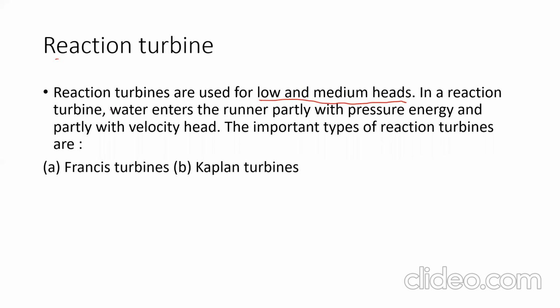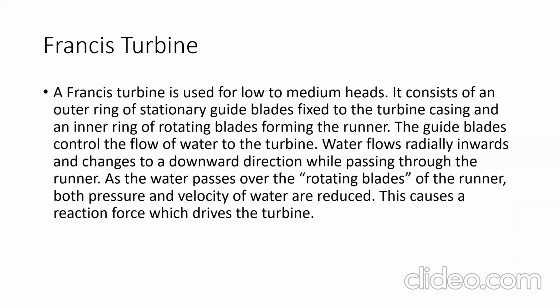Reaction turbines are used for low and medium heads, whereas impulse turbines are used for high heads. In a reaction turbine, water enters the runner partly with pressure energy and partly with velocity. High pressurized water with high velocity enters the turbine part. The important types of reaction turbines are the Francis turbine and the Kaplan turbine. I will show their photos as well.